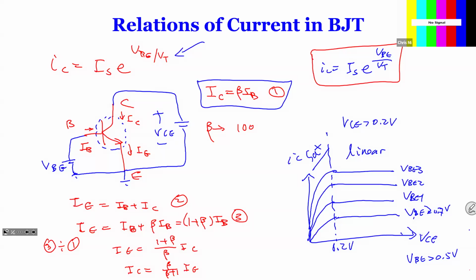So on Tuesday, we basically got an introduction of BJTs as we went through the physics behind BJTs, where you have two p-n junctions from base to emitter for NPN. So we have two types, NPN and PNP. A lot of them are going to be dealing with the NPN type, sometimes shortened as N type BJTs. And then there's a p-n junction from base to emitter, what looks like a diode, and that has to be forward biased,